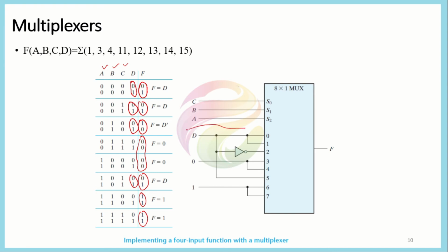The only thing that differs is how we use this circuitry, because the value should be either equal to 1 or 0. So depending upon what our minterm values are, we can easily design a mechanism in which we connect it to either 1 or 0 or to the input d. So these things are generally different for any given boolean function. The rest of the part remains the same.